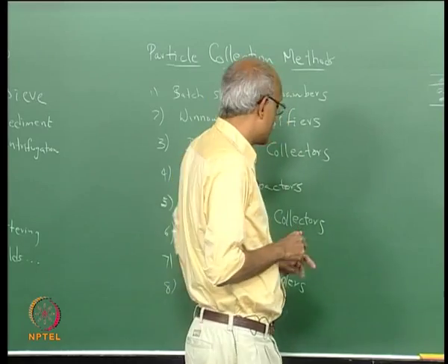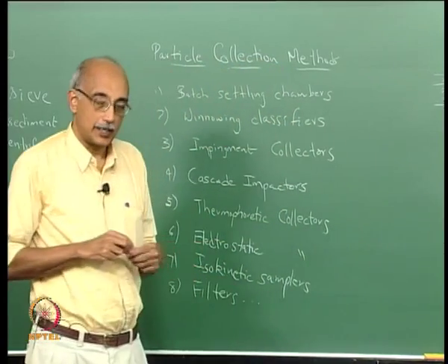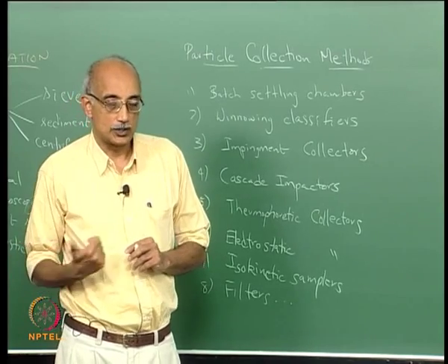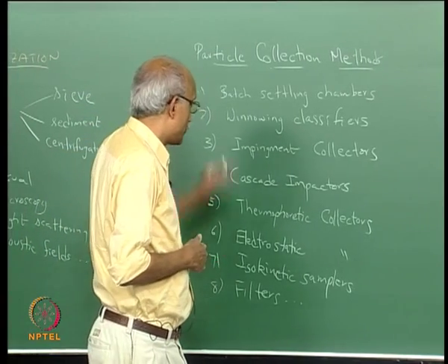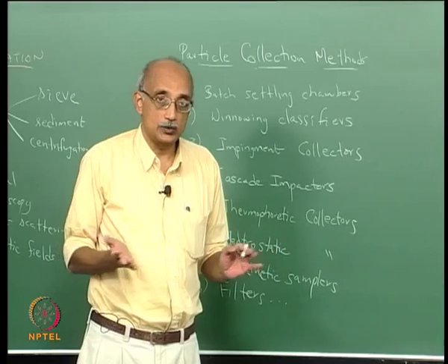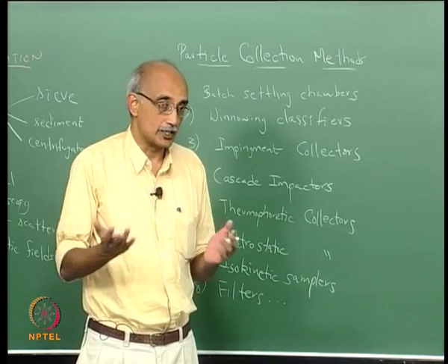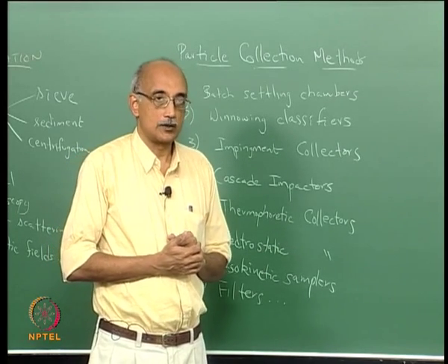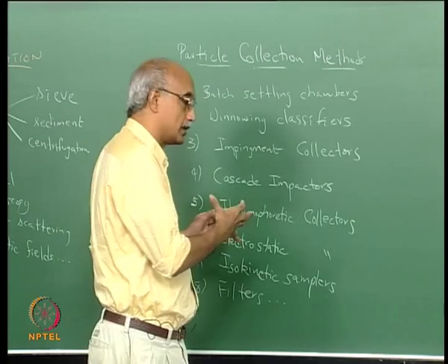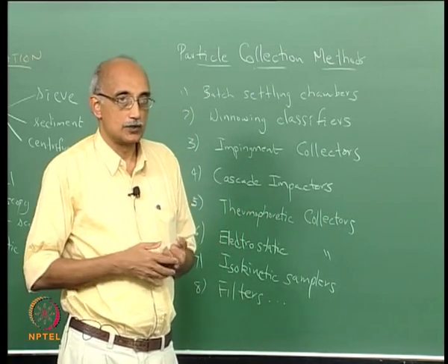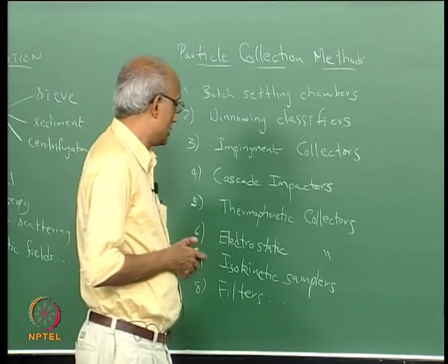So, there are some tricky elements involved in selecting the appropriate filter for doing the analysis that you subsequently want to do, but of all the techniques that we have listed, filters are probably the ones that are most widely used to collect particles for various purposes, whether it is for doing subsequent analysis or it is actually for collecting material, for example nanoparticles for use downstream in your process.